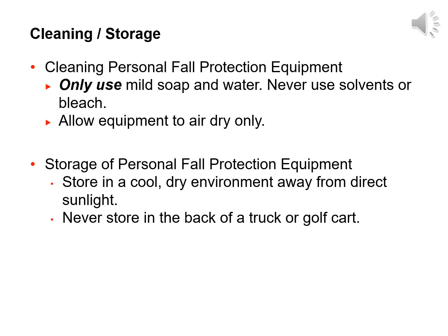It is understood that harnesses and lanyards will get dirty. If your equipment needs to be cleaned, you must only use mild soap and water. Solvents and bleach should never be used for cleaning because they can deteriorate the material. Equipment should never be subject to forced drying, but should be allowed to air dry only.